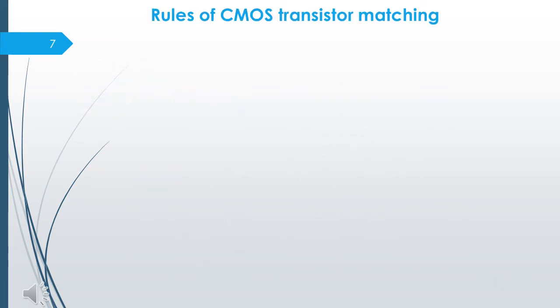The integration and miniaturization of ASIC, application-specific integrated circuits, play an important role in improving the performance and reducing the cost of electrical systems. Once the circuit specifications are fulfilled in the simulation, the circuit diagram is created using the virtual schematic editor. The resulting layout has to check certain technology-dependent geometric rules, design rules. Once the circuit has been designed, we can move on to the manufacturing stage. This figure illustrates the steps from schematic to fabrication.